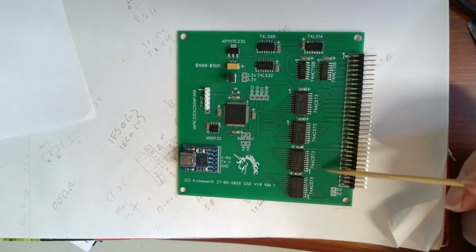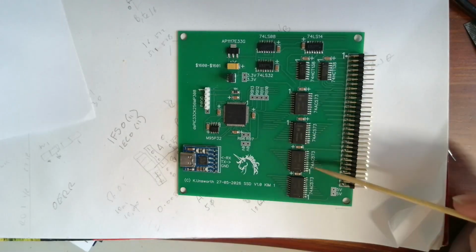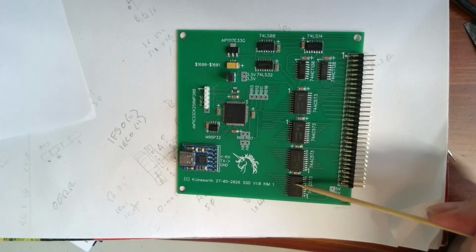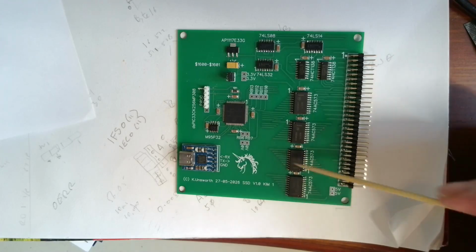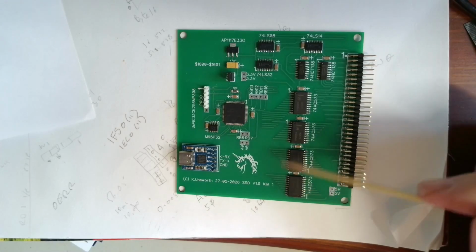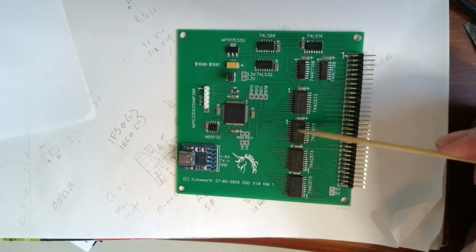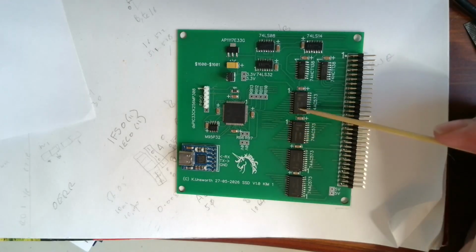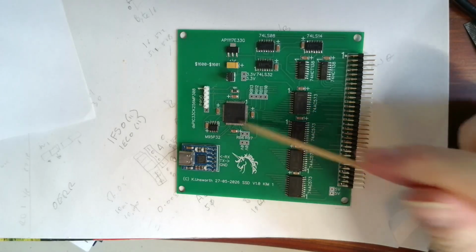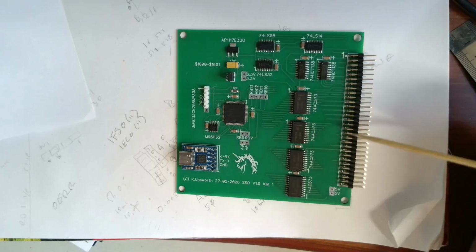So these use my favourite ICs, the 74573s, and the KIM can latch data into these at any time it wishes. And the microcontroller here will normally be scanning this to see whether there's anything coming up and then acting upon it. And when it's got anything to send back out, it will put the data out, and then it will put on the control here that there's data ready to be read. So that can write to these any time it wishes and they get latched in. So when this wants to read these, there's an output enable it can read, and when the KIM wants to read these, again there's an output enable going in that direction.